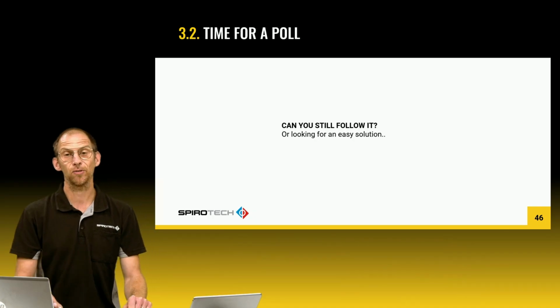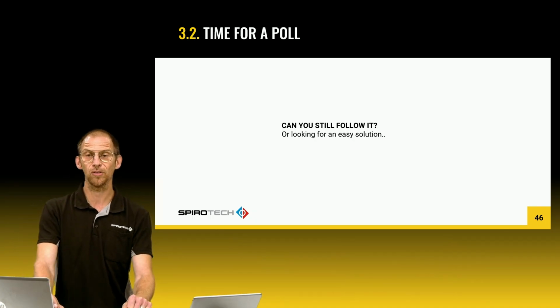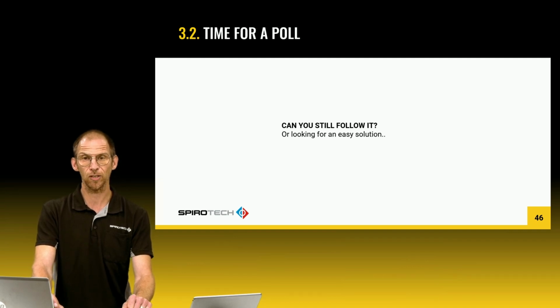And yes, you can crunch all of these by hand, all these numbers, all these calculations. You can follow EN 12828 and keep track of set points, watch the working range. It's doable, but it's also a lot of math and a great way to discover the one cell in your spreadsheet that decided to misbehave.